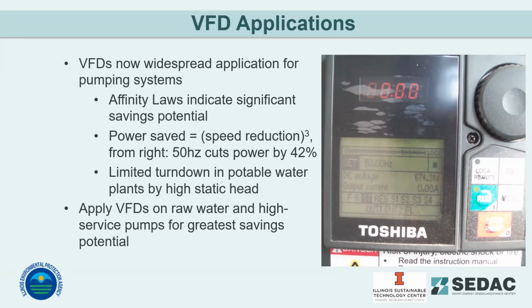A lot of times you don't think it's going to be that big of a savings because you're only turning it down 5%, 10%. But after that initial ramp up, the amperage and the hertz are lower, and you can save a lot of money over time as you're running that. So that's very helpful in a lot of different situations.